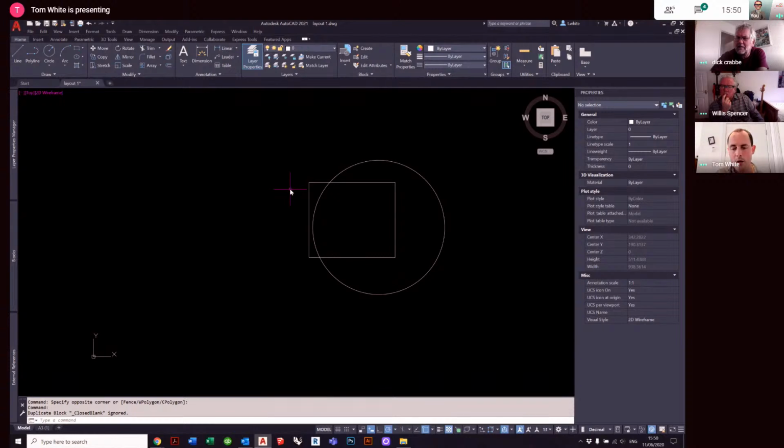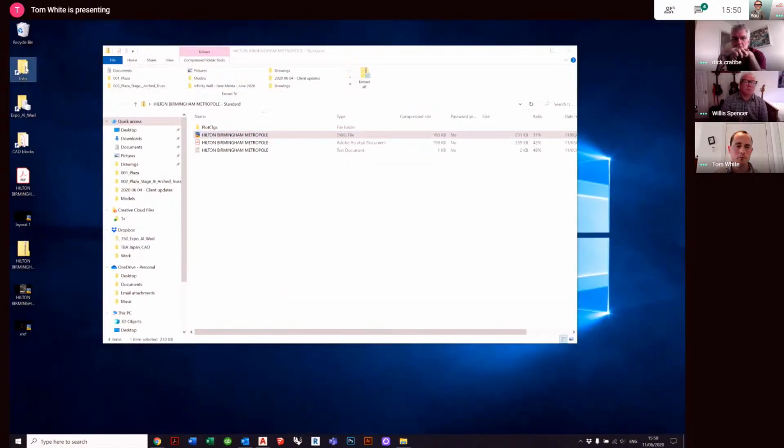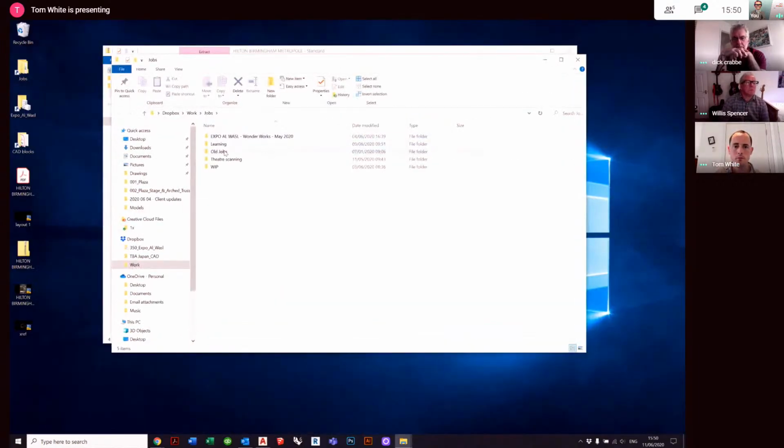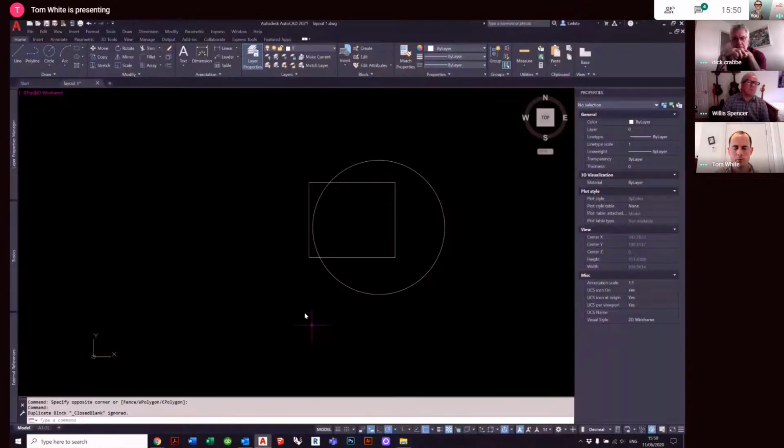Is that right? Necessarily, I sometimes send them out on projects that if the venue want to receive a drawing with everything in, and I don't know how good the CAD person is on the other end, or it may be just somebody who's got a license that's opening up. If I bind everything into the drawing at that midpoint, so I actually resave my drawing with a bind initial after it, because I don't want to muck up my original drawing. So I save as, give it a bound on the end of it, and then I will bind the DWGs, as Tom said, into the drawing at that point in time.